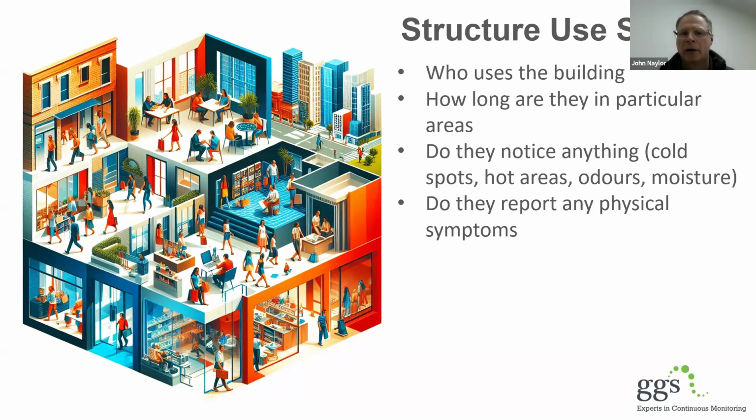Let's take radon for an example, which is a typical way that we see this. Radon is an issue for the actual persons exposed. It's not an issue for the building or the structure. It's you breathing radon in regularly over periods of time, and it can be very elevated in different rooms of the same building. So understanding where people are, how they're using it, and for how long they're using it gives you a great deal of information as to what their potential exposure is, and then what you could do to limit that while mitigations are taking place.